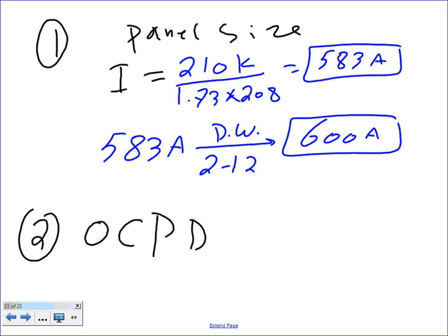Now, may I have a disclaimer? Say yes, Chad, we have a disclaimer. Probably only a fool will put in a 600 amp receptacle panel. So what would I do then? I would split them into 2, but we're not going to do that. Usually, guys, with receptacle panels you're going to stick with 225 amp to 300 amp panels. If you have larger than this, throw in another panel, and a third, and a fourth. But we don't care. We have a concentration of load in one area, and we have a 600 amp load. So we got the 600 amp.